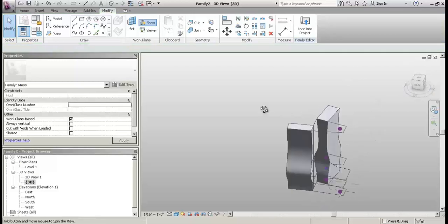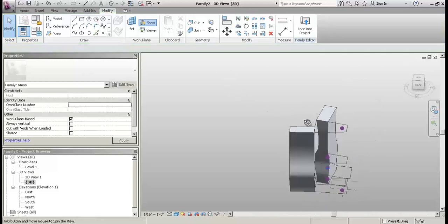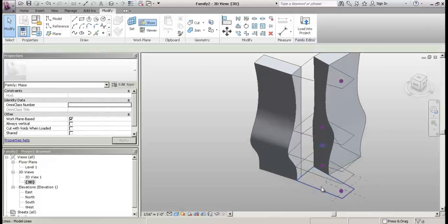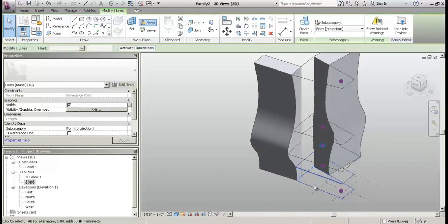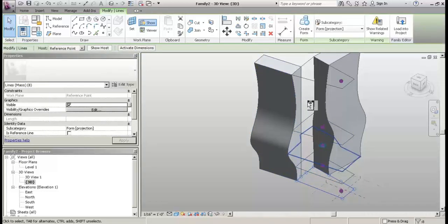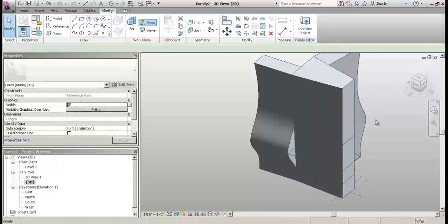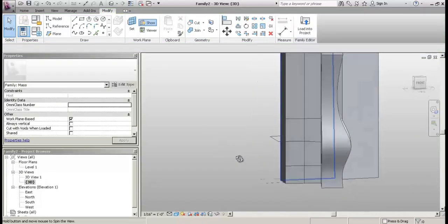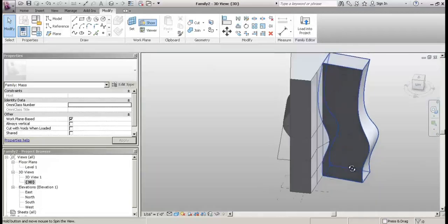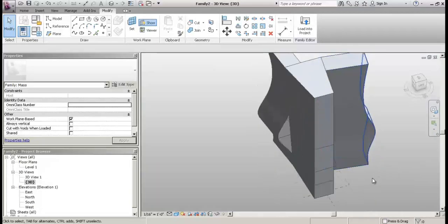What the dissolve command does is it gets me back down to those original profiles. So if I needed to re-sweep a new piece, let's say I was unhappy with that piece, or some of the stuff got a little funny, or I just wanted part 1 and part 3 up here, I can create a form in between those. So it allows me to go back in a few stages and get back to what I wanted or what I didn't have before.